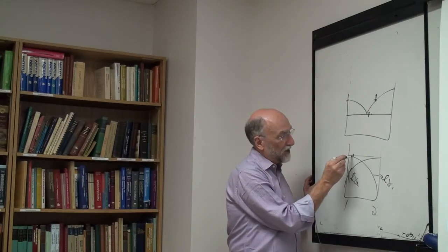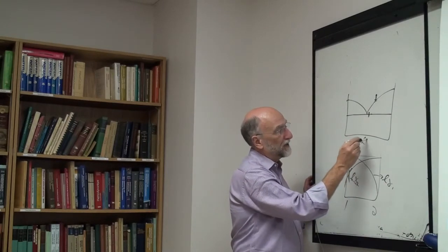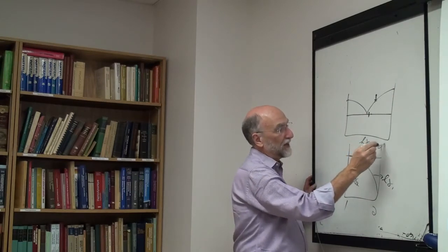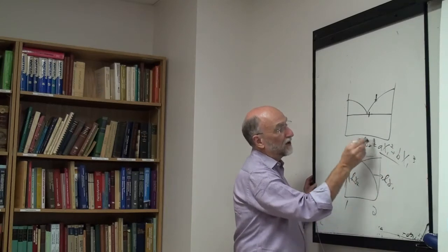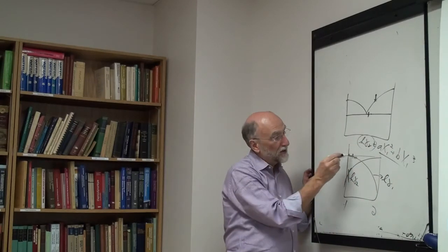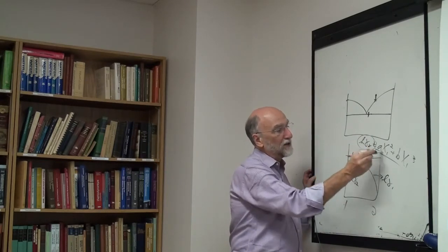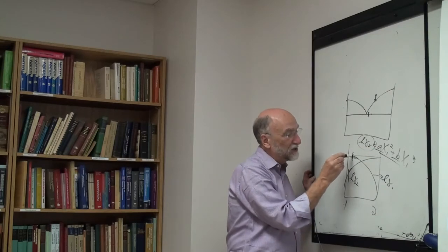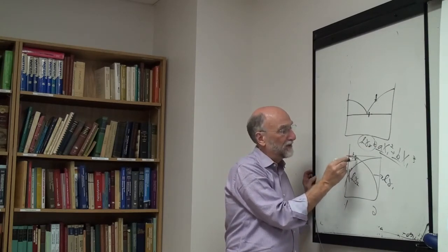So if you've measured log gamma 1, and you're doing a least squares, no matter what you do, you're fitting log gamma 2 to some sort of equation like a x1 squared plus b x1 cubed, and this is all going to go very close to 0 when you end up with pure component 1. Now you're trying to minimize the sum of squares, so the deviations from here, no matter what you choose for these parameters, you can't have much of a change. So these points end up being very important.